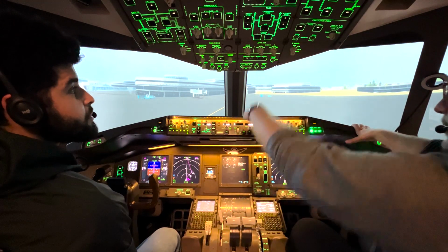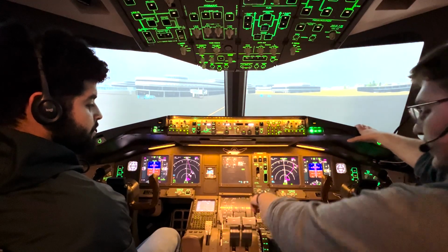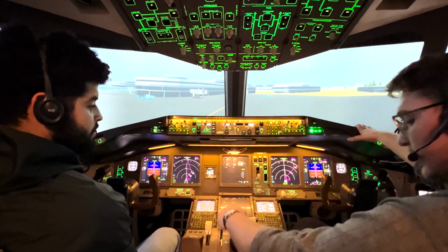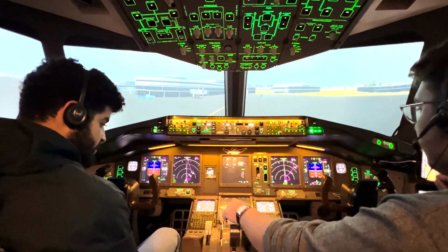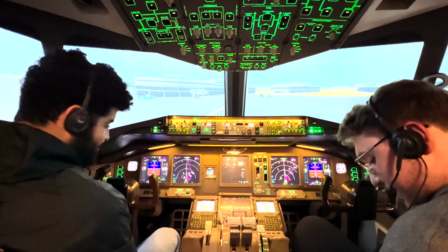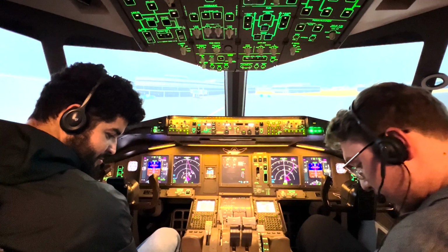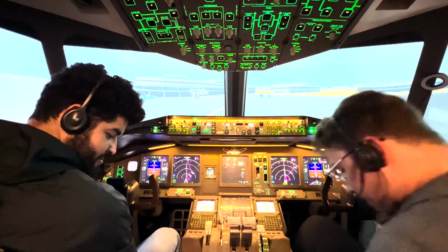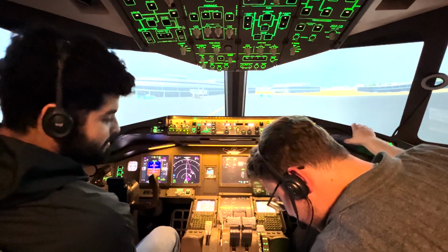So taxi lights are going on. Our auto brakes will be set to RTO. And we'll set flaps to 5. Landing gear is down in green. Flaps are in transit. TCAS is still off, so we'll go ahead and set to auto. TCAS is on auto, and we're going to do the test. TCAS test passed. TCAS sets TA/RA. Good.